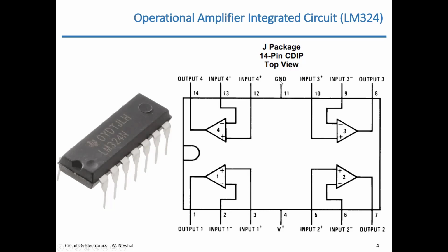So this chip, this data sheet, this is out of the data sheet, it calls VCC V plus. Okay. And it calls VEE ground. It's a little bit misleading because this ground, if you look in the data sheet, you could set this ground to a negative voltage. It doesn't have to be ground. It can be a negative voltage. And so that's why we're going to call this VEE. We're going to call this VCC. I'll be clear in my schematics when we talk about this, but you'll see data sheets with other variables used, other notation.